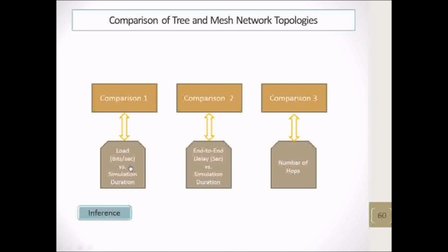Now this is a VISA. VISA stands for virtual instrument software architecture. Suppose it is a temperature sensor, the VISA block sends asterisk to the COM port and returns values associated with asterisk from the COM port to the other blocks, and asterisk is a default value for temperature sensor.